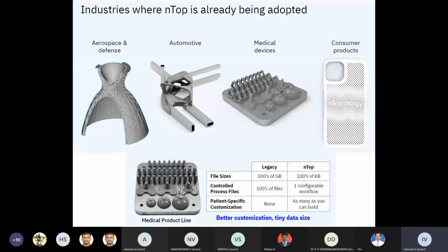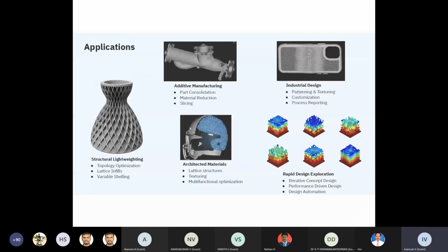You can create trabecular structure. Our natural bone is porous, and that porous level part is trabecular. Recently I did a trabecular design for an acetabular cup for one of my clients, and I was surprised. I developed it in 10 to 15 steps, creating various parameters: pore size, inter-distance, everything.